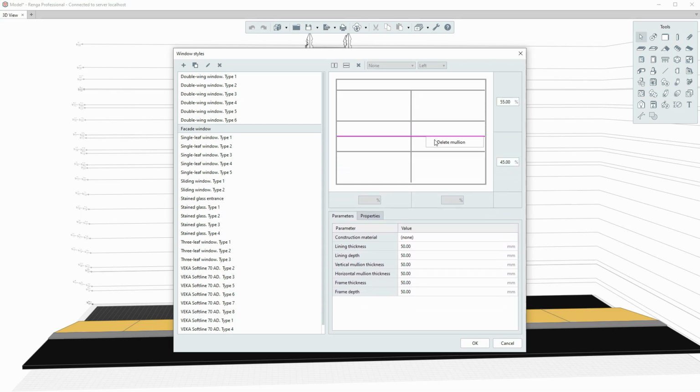When a mullion is deleted, all the mullions and frames that are located in the area formed by it are deleted. In order to assign property for frame, do the following. Select the area to which you want to assign the type and orientation of the frame. Specify frame settings in the drop-down lists that open in the upper part of the window. The selected settings will be schematically displayed in the editor. If the frame properties are specified for the area, you cannot create mullions on it. Select the None frame type to change selected area.